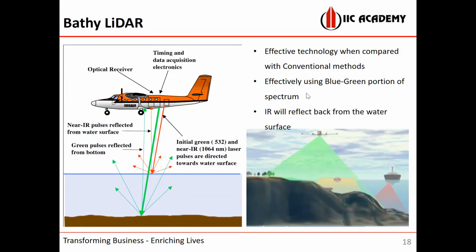To cover the Red Sea area, we did a survey of the entire Red Sea. We took almost 3 years with a hydrographic multi-beam survey. Whereas the entire Persian Gulf, we covered in just 13 days. But another disadvantage with this bathy LiDAR is that we cannot do deeper regions. It will penetrate up to 50-meter depth only. Beyond that, this technology cannot be used.